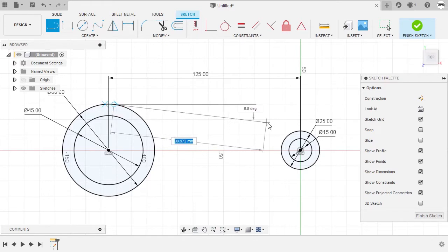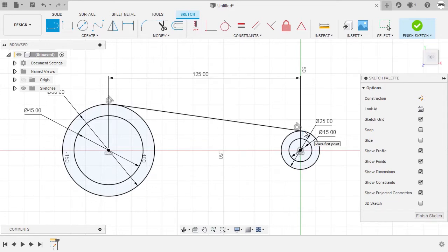Let's head over to the other circle at the right and notice as I hover over and see the intersection and move to the right, I am seeing another inferred tangent. This time I'm going to release, repeat the procedure, hover over the circle with the intersection visible, holding shift and the left mouse button.